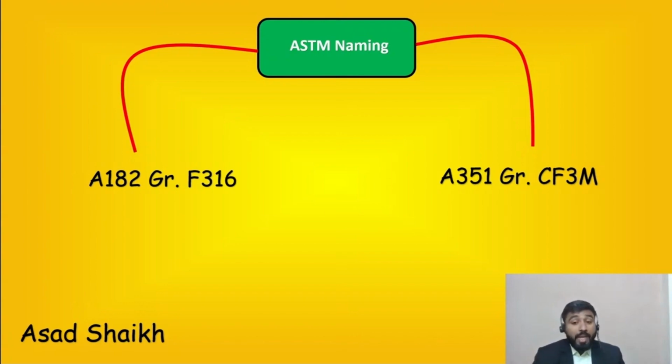As an engineer, why I stressed this point is, I would not name them, but after talking to a few vendors, there are certain companies for whom, for a certain valve material, they want it to be forged. So if the vendor has given the cast version of that valve body, it was rejected at a very late stage.